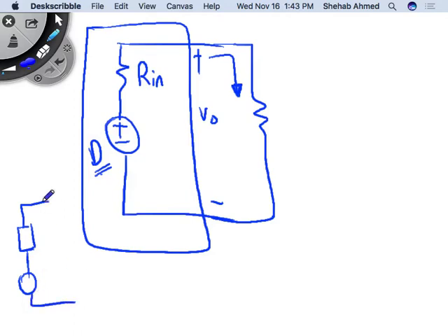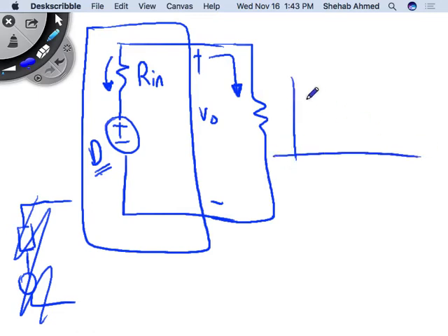But any voltage source can be modeled as an ideal voltage source and theoretically an impedance in series. It's an impedance in series. If we have AC, then this is an RL impedance. If it's a DC circuit, I don't care about L anymore, I just talk about internal resistance. So any source looks like this. If I increase the current being drawn by the load, there will be a higher voltage drop here, so the output voltage that the load is seeing will drop. Do you agree? Yes? And this is called voltage regulation.